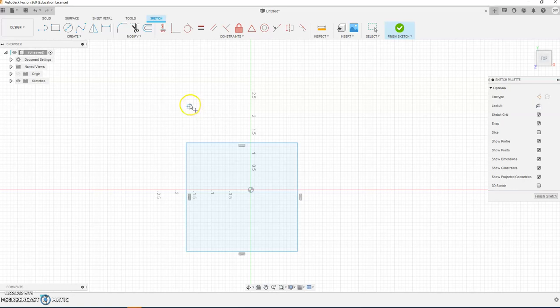So the first thing we're going to do is work towards locking it in place for the position. To do that, I'm on the point command, and I'm going to hover over this line. Notice when I hover over this line, it gives me the little nearest box or OSNAP. We're used to that from CAD. If I go here to the middle of it, slide close to the middle, notice what happens. A little triangle shows up. So if I click there, I'm going to put this point at exactly the midpoint of that line, and I want to do that.